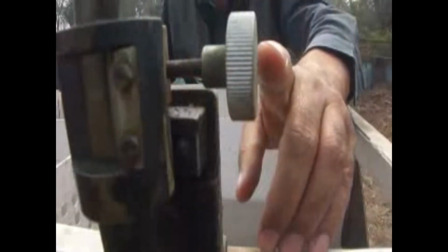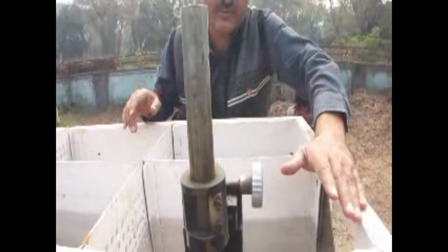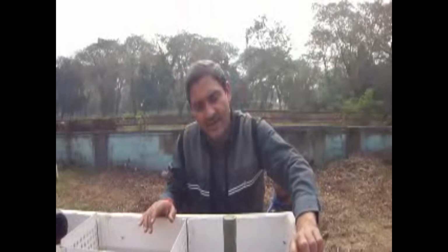And okay, so you can see it is zero flow condition now. So we can read from the main scale and vernier scale. So in main scale reading is 9.3, and you can see which of the vernier scale is matching with the main scale, that is 8th. So it is 9.38 is the reference head over the crest we have measured. So if we are taking the difference between these two, 9.38, and the first we have taken 12.98, then that is the head over the crest because of which the flow has occurred.